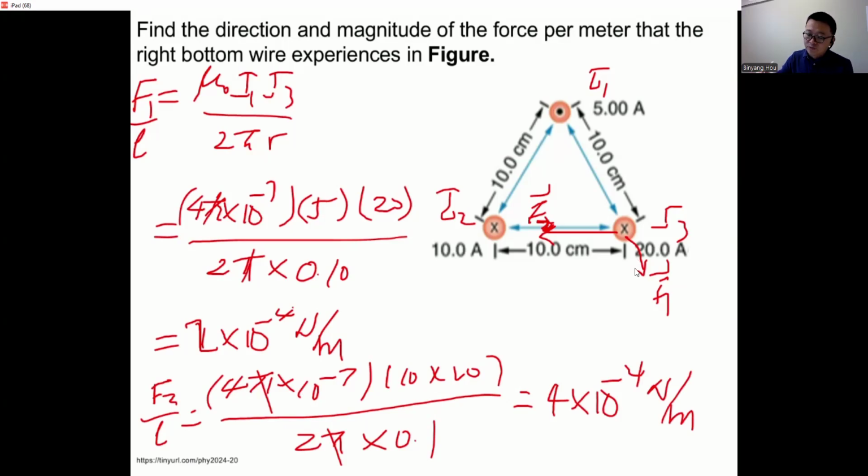All right, so now we can do the x component of this one. According to geometry, this one should be 60 degrees below the horizontal. So you can do F1 cosine 60 for the x direction, and F1 sine 60 for the y. Then add F1x to F2x. F2 will be purely in the negative x direction, and then F1y plus F2y, where F2y will be 0.